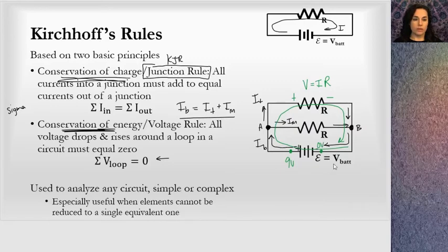And if I go around in the circuit, I can see that I get V bat minus V across the resistor has to equal 0. And so 9 minus 9 equals 0. So that resistor is getting 9 volts. This is a parallel circuit, and that should make sense for us.